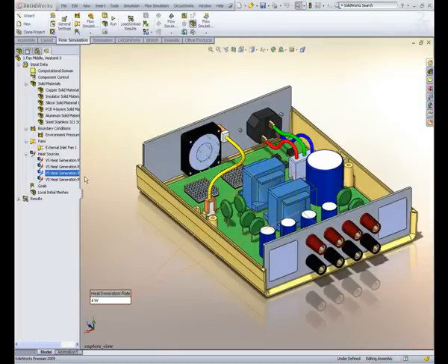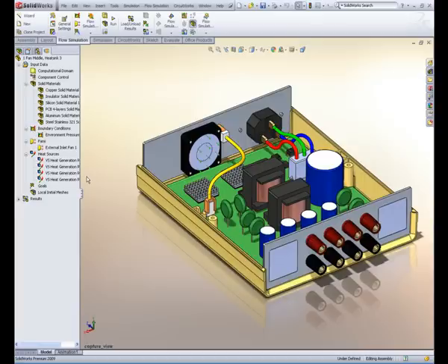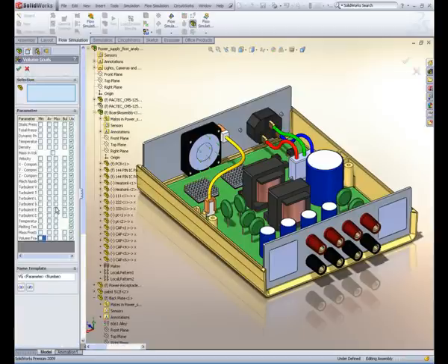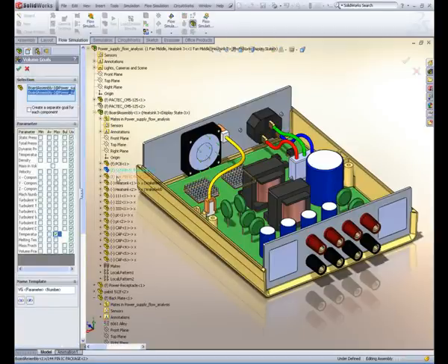Now that the flow test is set up, we should consider what we would like to measure from this test to see if our present design is suitable. Seeing as the major use of cooling fans is to prevent the internal components from overheating, we can set up a goal to measure the maximum temperature in the two CPUs.